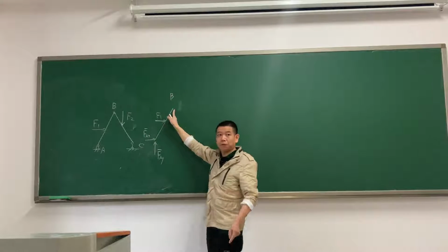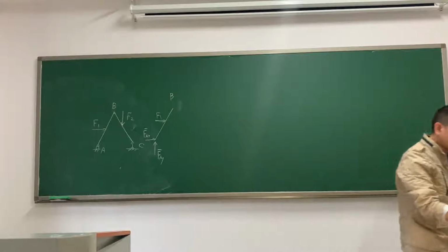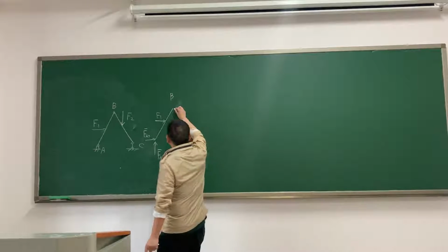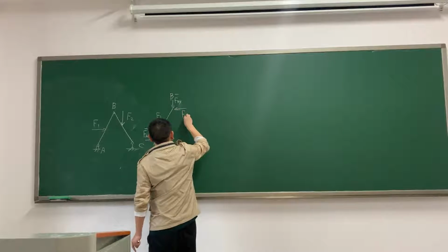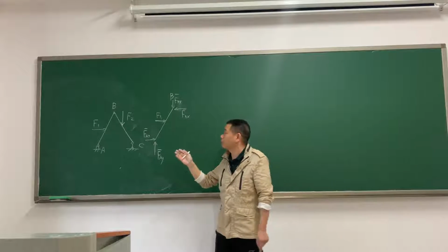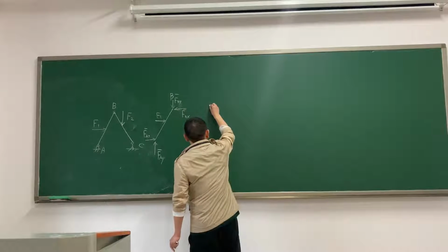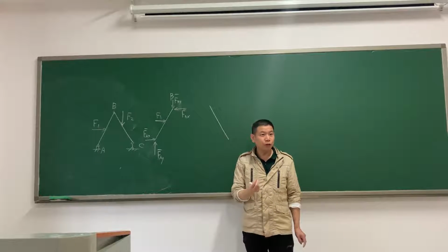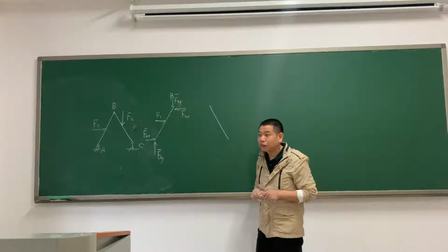How do we draw the reaction at this point? Because it's a pin connection. You're clever. FBY, FBX. Each is a free-body diagram. The first step is to draw the member and remove all the surroundings.